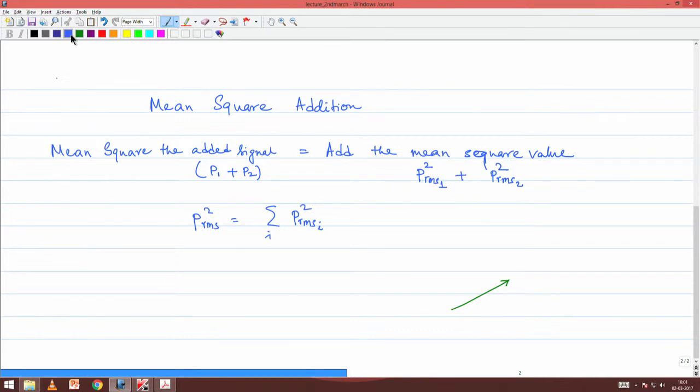For two sources, I will draw two phasors which have a phase difference of beta 1 minus beta 2. Both of them are going to rotate at the angular frequency. The addition of these two is just a vector addition of the two phasors, which is going to rotate. As you know, the vector addition of two vectors depends upon the angle subtended by the two vectors. Therefore, the resultant phasor will depend upon the cosine of the phase difference.